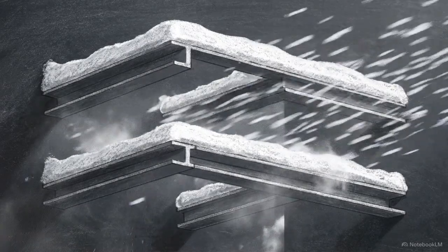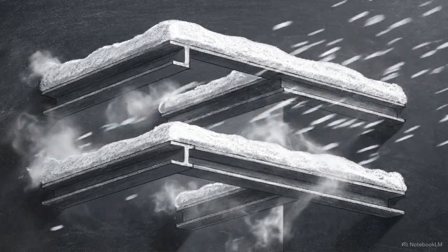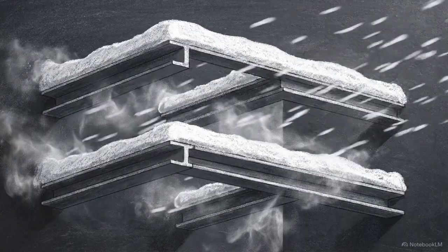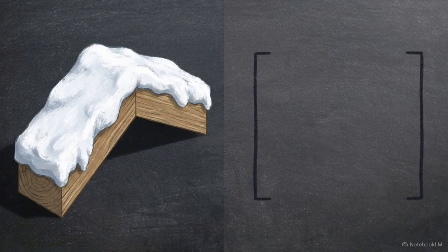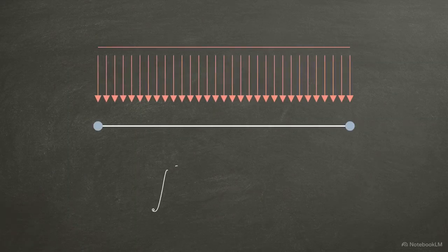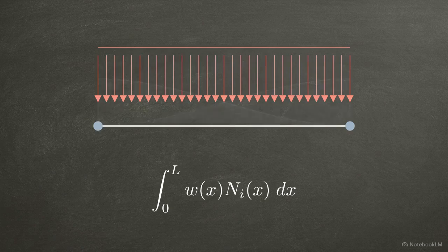They press continuously along the span of the beam, often missing the nodes entirely. We need a way to translate these continuous loads into discrete nodal data. We calculate equivalent nodal forces using integration. We integrate the distributed force across the element's length, weighted by shape functions.